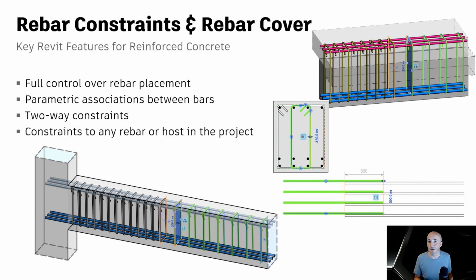You can change rebar covers for the whole element at once or for individual faces of the concrete element. When placing rebar, either directly or by sketching, the bars will automatically snap to the concrete cover or nearby bars. This behavior also applies when adjusting the bars by dragging individual bar handles.